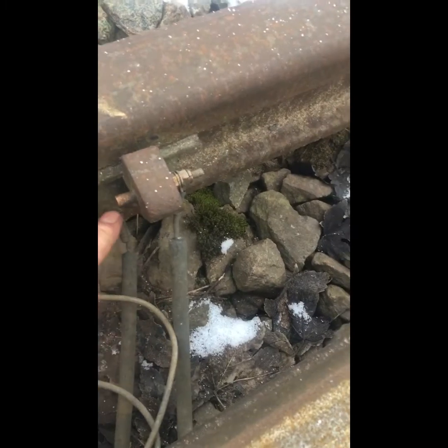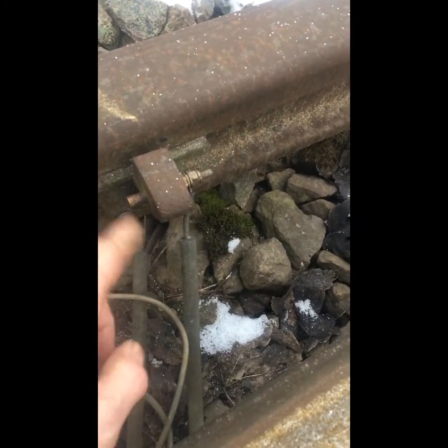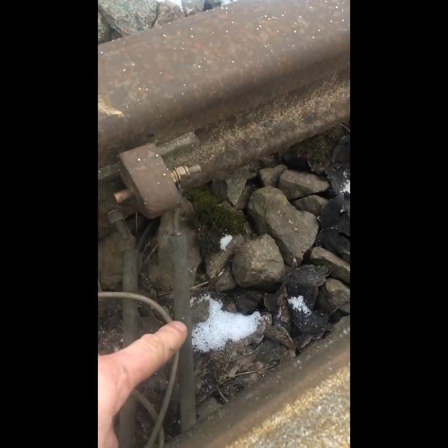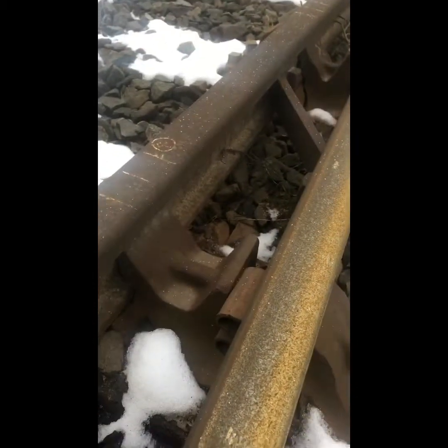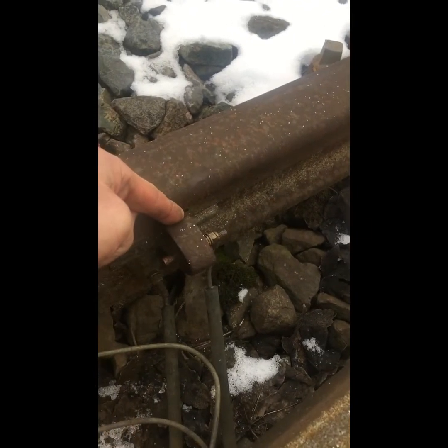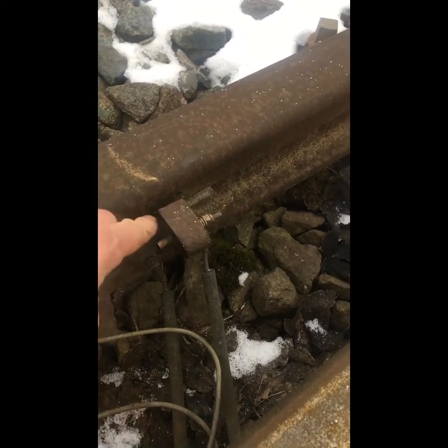Here we have our insulated interrupter, as we call it. One leg comes in onto the rail, which is insulated, and then we have the knockoff piece on the other side, with the other leg going back out. As you can appreciate, if a train runs through the points, the flange of the wheel will shear this off here, knocking it off. This is a track circuit interrupter in its various pieces.